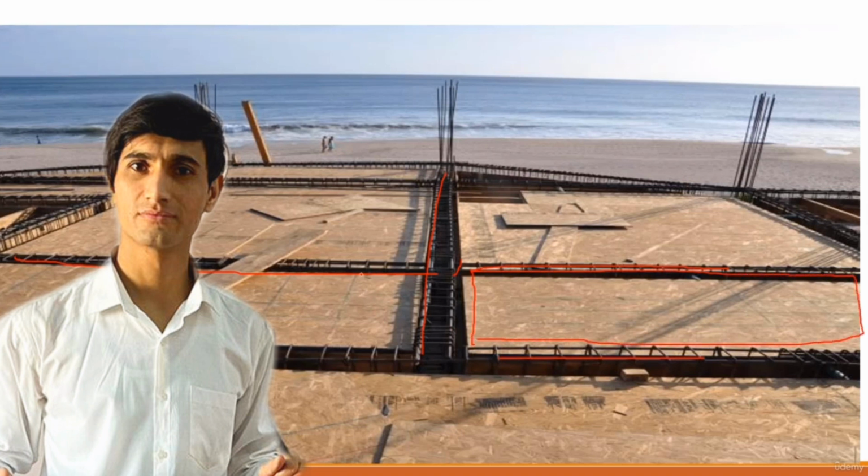All we need to do is find out the inner portion between the beams, and it is important to check the top beam plan, and from there you can calculate the formwork quantity. So in formwork quantity what we need is area. For area we just need the length of the formwork and the breadth of the formwork. It could be a room here, it could be a shop, anything. So all we need to do is take the length and the breadth in order to find out the total quantity for the formwork.